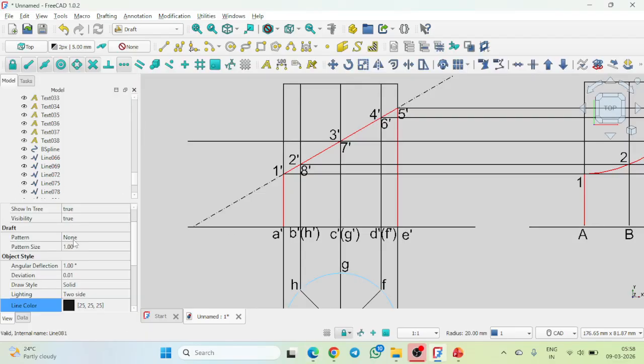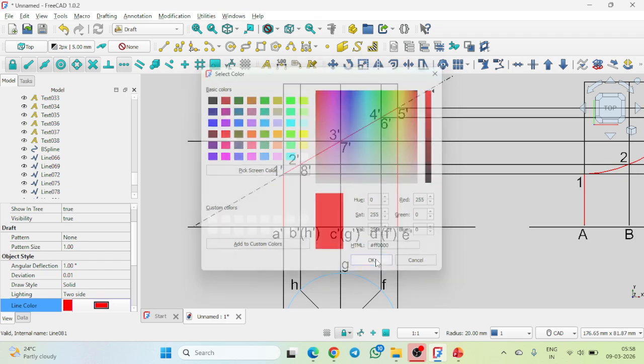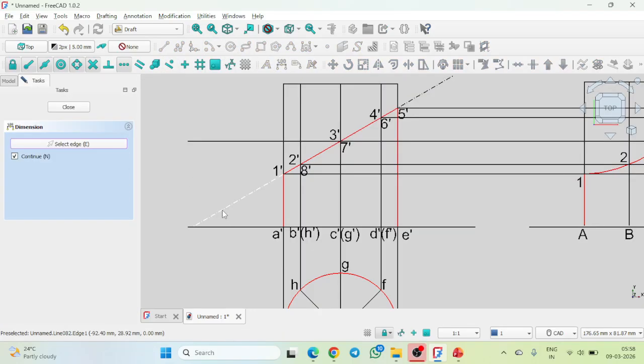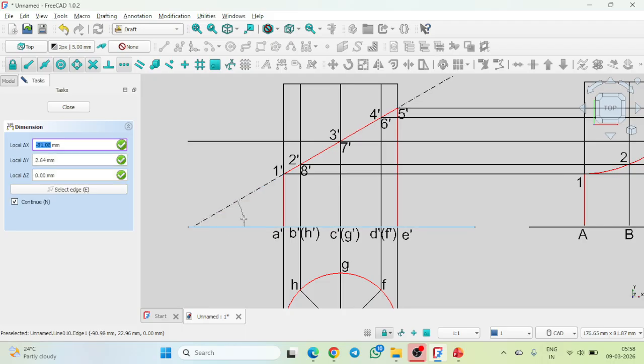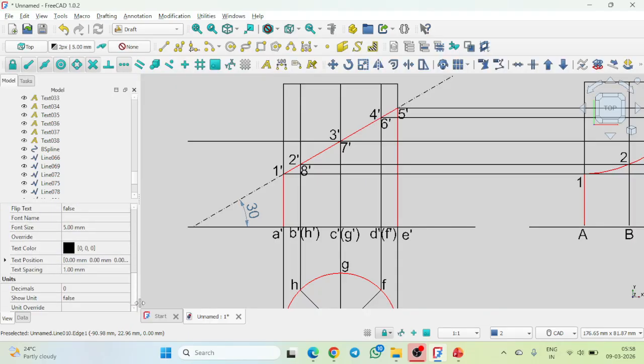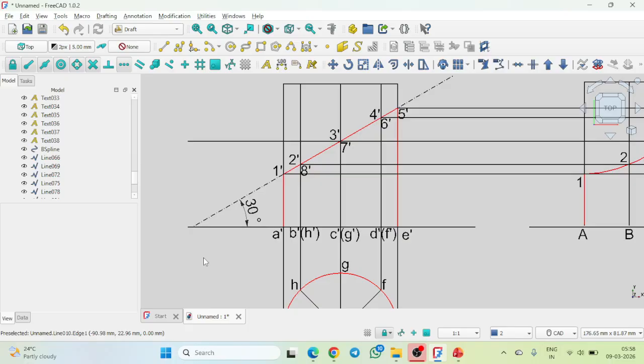So similarly the circle color also can be changed. Okay. So now the dimensioning has to be done. That means select the alt command, select these two lines. I can give some extra. Okay, so reduce the arrow size. Let me go with the 0.5, check it with that one. Yeah, it is somewhat okay. I can give 0.6. Okay, then I can give the show unit. Right, so this has also been done.